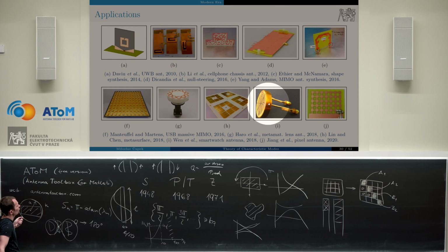Okay, here it's just a loop, but let's consider that this loop is made of extremely many discretization elements, and then the impedance matrix is huge. So it makes no sense to decompose it into characteristic modes, because it will take a lot of time. But if I know from the beginning where my final excitation feeders can be placed, like here, I can compress the problem a lot.